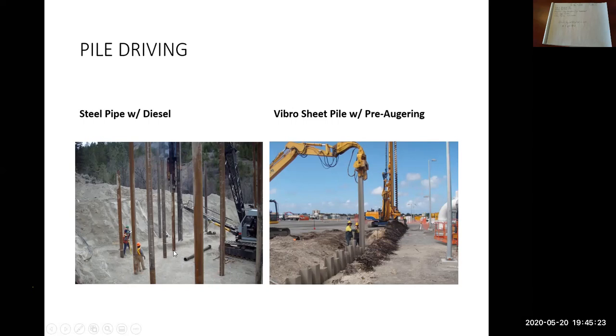So this crane is installing pipe piles. Looks like with a drop hammer or a diesel possibly. So really heavy weight is dropped and it pounds the pile into the ground, is basically the thought process for drop type hammers or the diesel type.